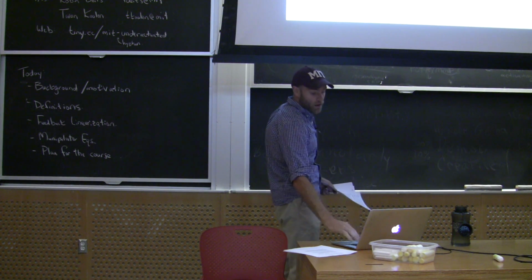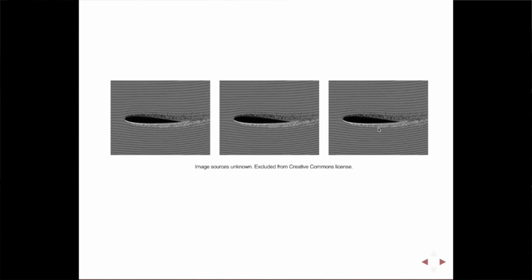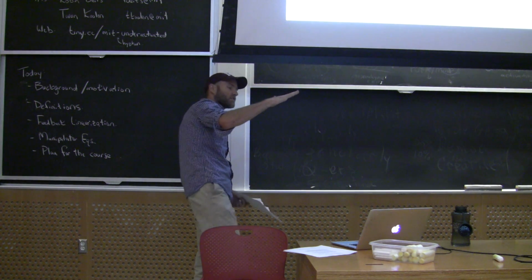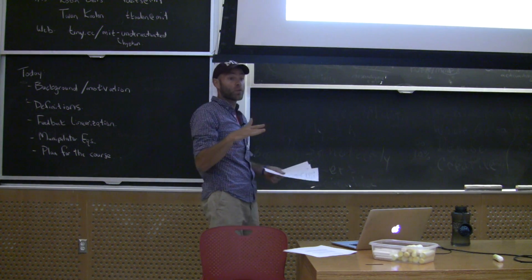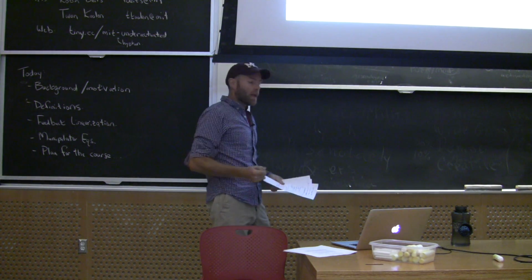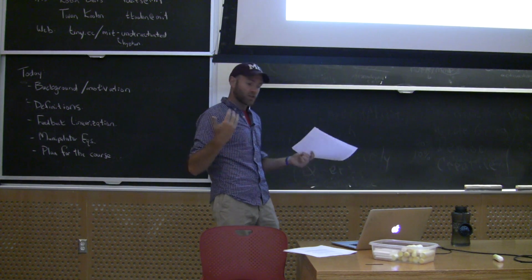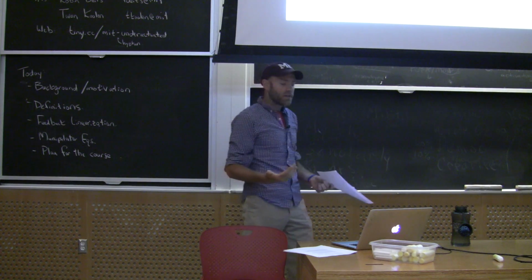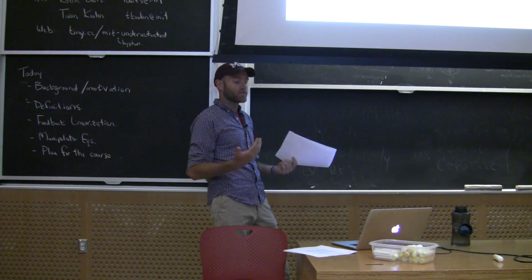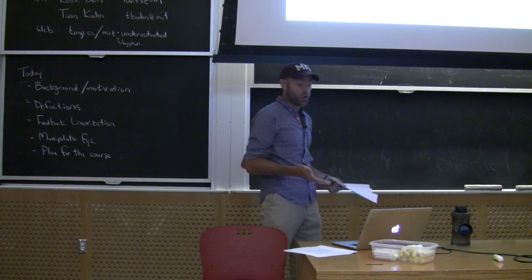And if somehow the images didn't actually update, that's too bad. This one's supposed to be a stalled angle of attack, okay? If you raise your wing to too much of an angle of attack, the air basically can't bend around the wing. It will separate, and you'll get a vortex shedding phenomenon. And what happens in the modeling, if you care about designing a control system, is the system becomes very nonlinear, okay? And effectively, we haven't had good tools to control those systems.